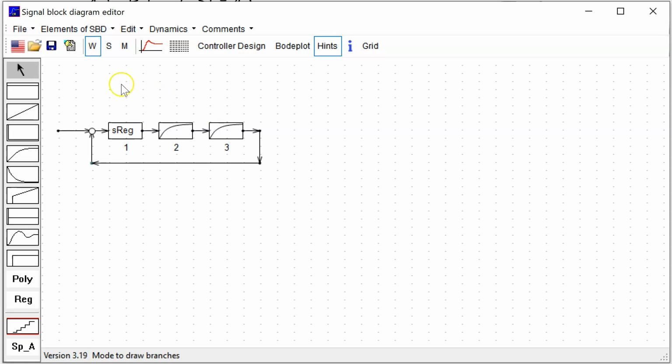The next step is I need a minus sign. Go to minus sign point. You see then automatically the branch mode is disabled. And if the minus button is marked, then I have to look for a branch, click with the mouse exactly on the branch, then this branch gets an inverter. In the drawing you see there is a minus sign, and automatically the minus sign mode is disabled, so you can only set one summing point, one minus sign, but multiple branches.